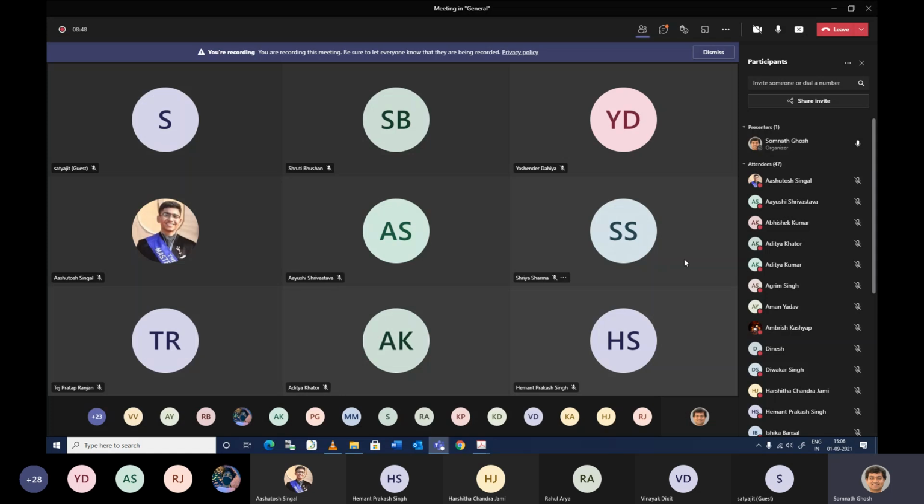Anyone? Sir, the first one is the delta P term, that is due to the external pressure. Yes, so the pressure force is there. That's called the pressure gradient, which is also compressive in nature. There are other terms, right? From Newton's law of viscosity, you can also get the viscous term, right? What are the other terms? There is another term. Sir, the body force, rho g. Yes, rho g is the body force term, right?